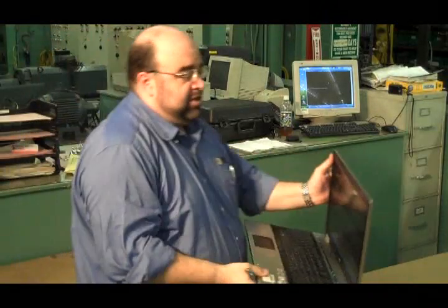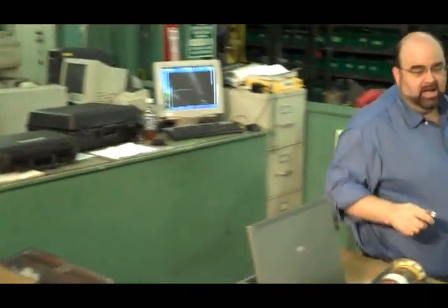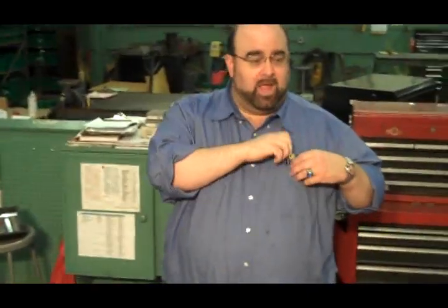So as you can see, technology has gotten very, very flexible nowadays, to the point where the electrician or the troubleshooting person is not limited anymore to just the multimeter and the megger. And what's very important about all of these technologies we've covered is that they're flexible for virtually any type of application. For systems over 600 volts, you would go in with live testing. You have to use current transformers, the CTs, and the potential transformers, or PTs, to collect your data, because none of the manufacturers make anything over 600 volt capable.